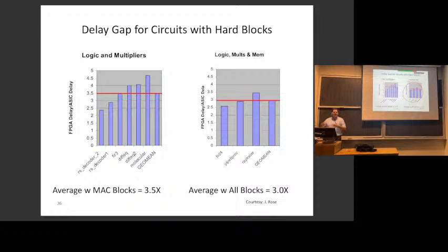So, and this is something we saw at Altera. These numbers do line up. When we put DSP blocks in, so blocks that could do hard multipliers, for designs, they are a lot more efficient, around 10x more efficient than building it in the programmable logic. So if you exactly used what we put in the DSP block, you got about a 10x area reduction for that one function. But we didn't get much speed improvement for this exact reason. There's still other critical paths in the rest of the design, so it doesn't speed you up much.